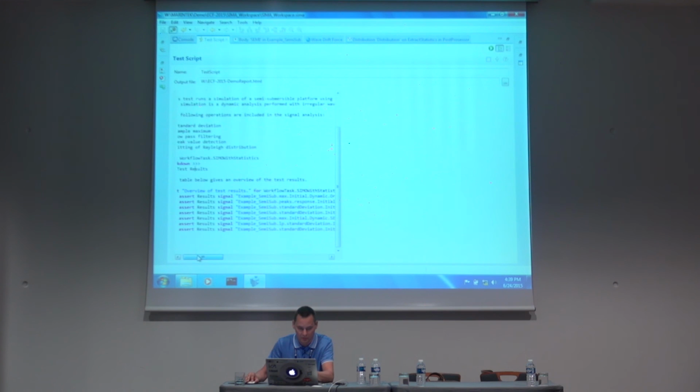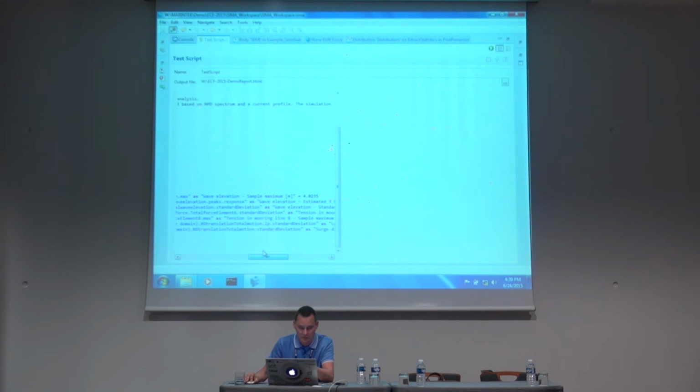So results, signal, and there's a long string. As means presented as. Don't write this terribly long string, but show it in the table as this. And it has to have this value. And the standard deviation, that can vary a little bit depending on the numerical issues with physics engines, but usually this is quite okay. So we only test a very narrow piece of the simulation, but if something is wrong here, then we know we need to dig into things.